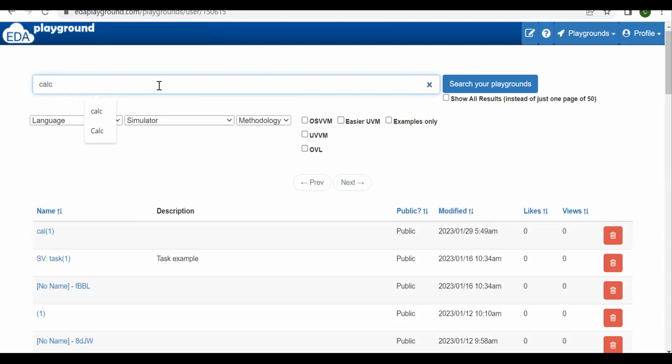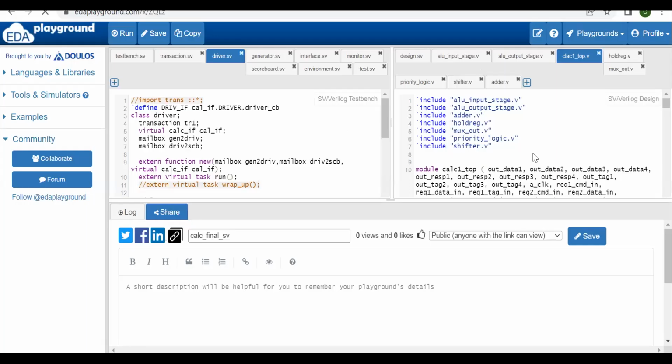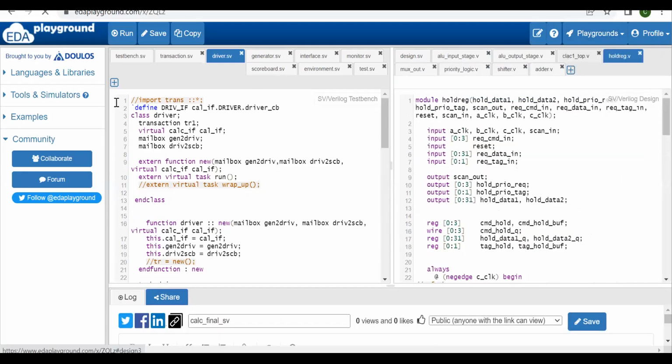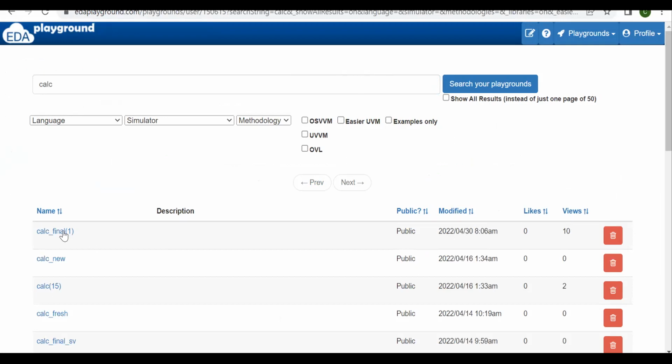Have you practiced? Can you tell me what blocks we have in UART? What is the frame format of UART? Can anyone tell? Start with the data bits, parity, and stop bits.